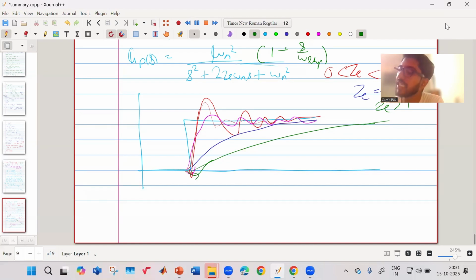Your controller will start taking action. And when your controller sees that your voltage has dipped, it will increase your duty. Right? No. You are actually increasing your reference. But then what is happening? It is going in the opposite direction. When it should actually increase at the start, it is reducing at the start. So that acts like a delay. It's kind of like a delay is added.